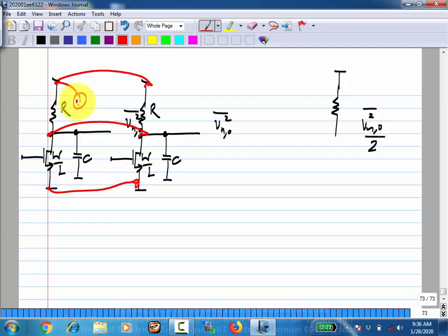You can directly get it from the noise spectral density of R by 2. Wherever you have these two noise currents that are uncorrelated, whatever spectral density this has, if you make two copies, the current noise spectral density becomes 2 times higher. Now what happens to the impedance level at each node when you put two circuits in parallel? Half. So what happens to the voltages? It is current noise spectral density times something related to the square of the impedance. So it becomes half. When you put two circuits in parallel, node by node, all the voltage noise variance or spectral density becomes half of what it was before.